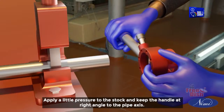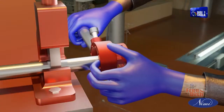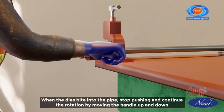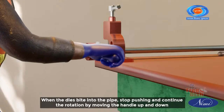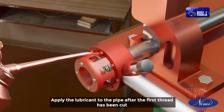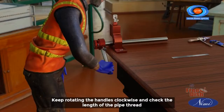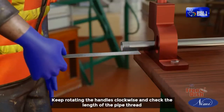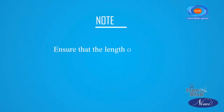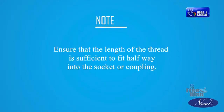Apply a little pressure to the stock and keep the handle at right angle to the pipe axis. When the dies bite into the pipe, stop pushing and continue the rotation by moving the handle up and down. Apply the lubricant to the pipe after the first thread has been cut. Keep rotating the handles clockwise and check the length of the pipe thread. Note: ensure that the length of the thread is sufficient to fit halfway into the socket or coupling.